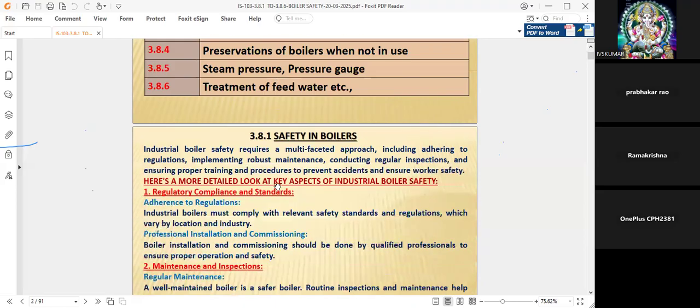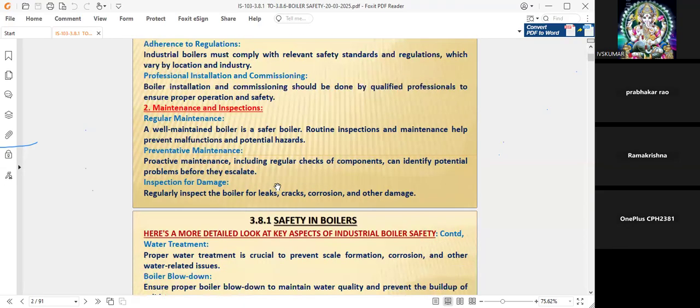But as per your question, the maintenance does not follow any schedule within the industry, sir, because the inspection by the inspector of factories has to be carried out every year. Depending upon the date fixed by the inspector of factories, they will pre-plan the boiler shutdown and the connected plants and procedures. There is no maintenance schedule for this.